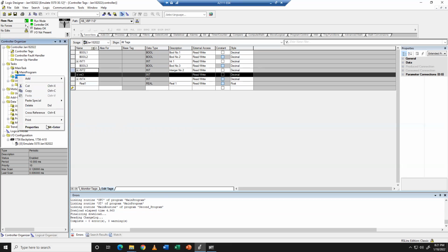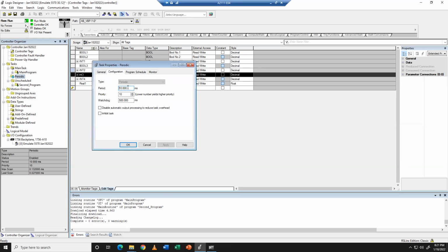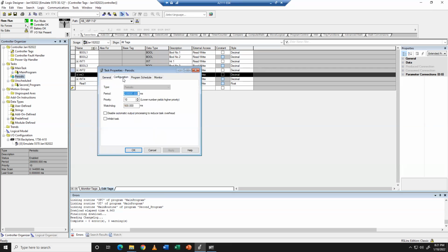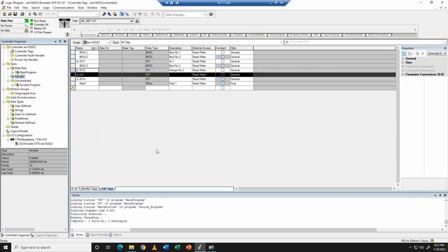The limits for them, you can see, again, it's in milliseconds, but I think you can go up to like 2 million milliseconds. So you can really drag that out. You can do a couple of hours. Again, this isn't clock time, it is cycle time based on when you turned on. So if you need something to happen like every 5 minutes on the fives, this isn't what you want to do. But if you just need something to run periodically based on the last time the processor turned on, and then it does have a